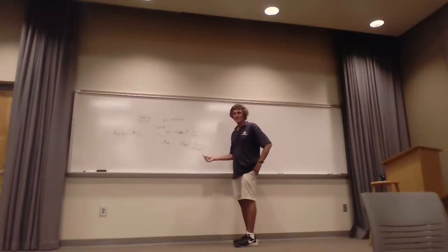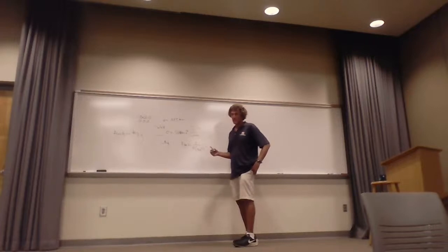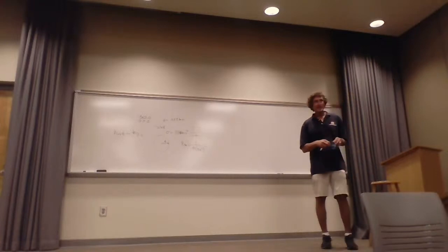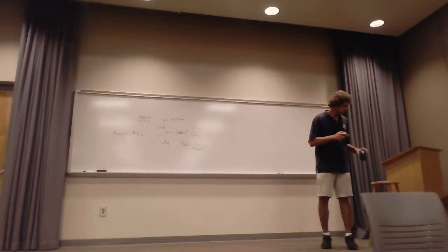Sigma is 5.8 times 10 to the 7th, multiply that by pi a squared, and A is 0.25 millimeters, 0.25 times 10 to the minus 3rd. And make sure you square it. You'd be surprised how many people make mistakes on this simple calculation. What'd you get? That's square, not cubed. Went a little too far. Again, 0.0878.